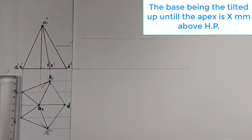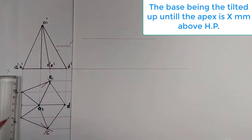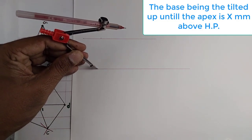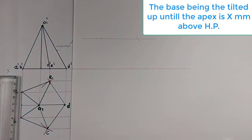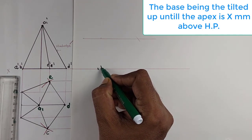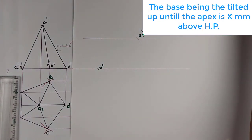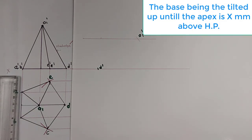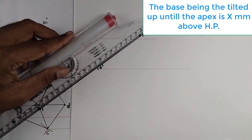So for that, I measure the radius D dash O1 dash. When the base is tilted, the corner D of the base stays on HP. So we choose the corner on HP and we can draw the arc. So we write the names of the points. It is our D dash and this is our O1 dash. Now I join D dash O1 dash with a straight line.